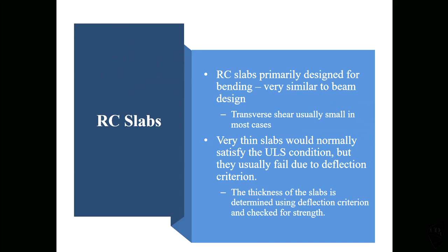The bending, flexural reinforcement design is the same as beam design. There is no difference. And we don't need any shear reinforcement. Usually slabs don't need any shear reinforcement.